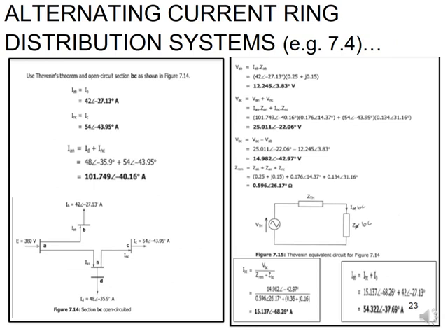Only then can you use your open circuit section in order to calculate. Because in this case you first started with a conversion of your delta to your star, if you chose the bottom part to do that conversion, then your Thevenin theorem must be used on the opposite part, which is your top part. If you chose your top part to do the conversion, then your Thevenin theorem for open circuit is going to have to be at your bottom section.